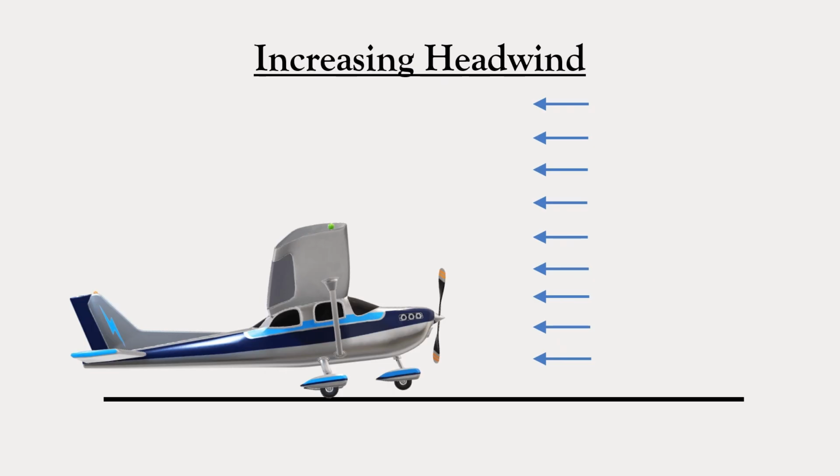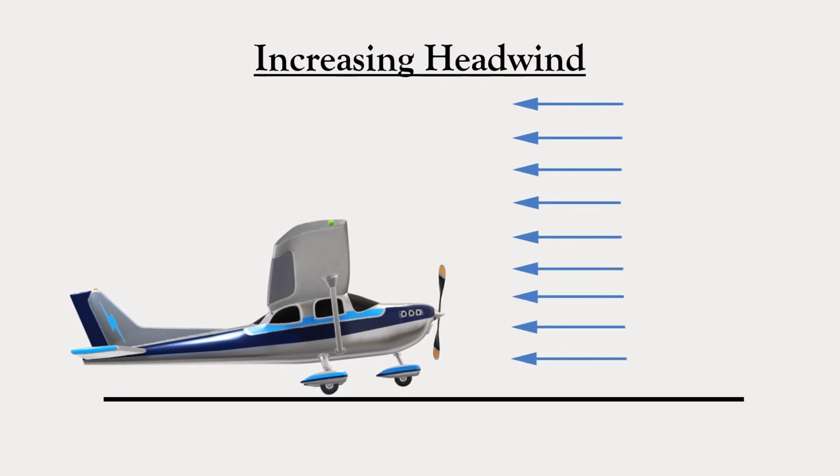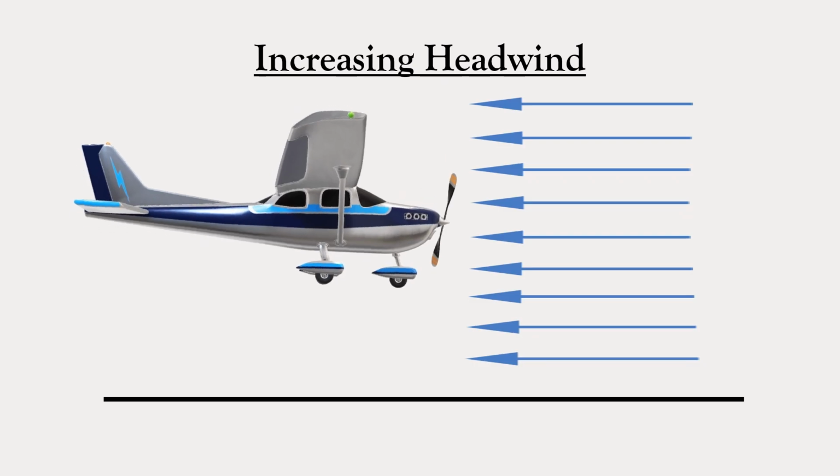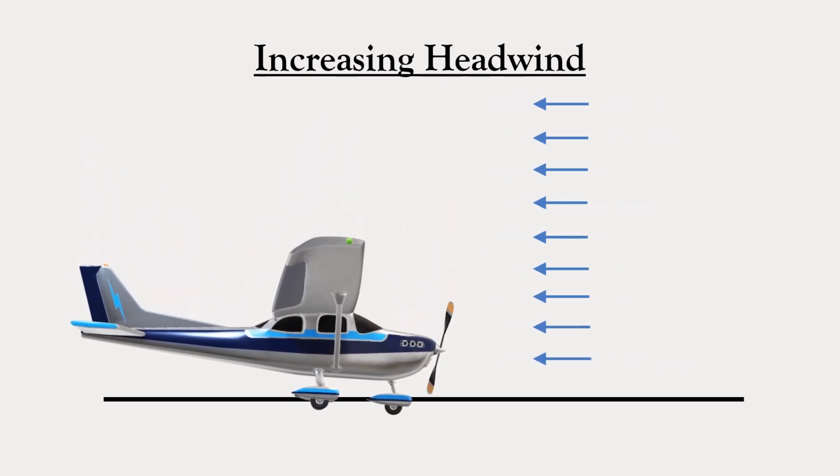Here, as the airplane is accelerating on the runway, a wind gust suddenly increases and the airspeed is enough that the airplane lifts up. A pilot that's surprised by that will tend to push forward on the stick. Since gusts are temporary, this headwind component may go away as fast as it came, may even turn into a tailwind component. The airplane sinks back to the runway.